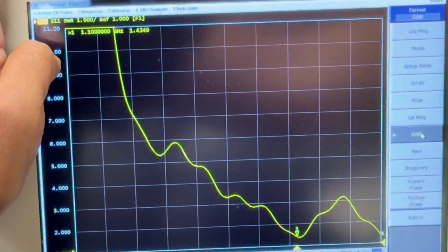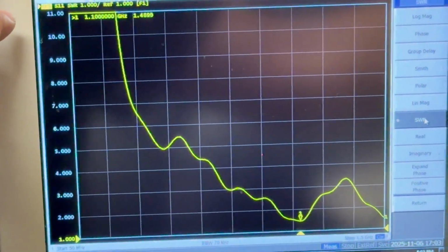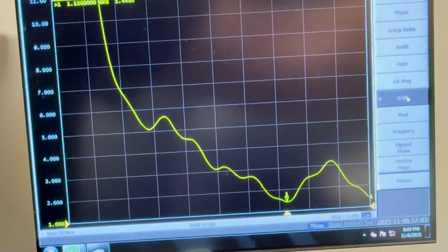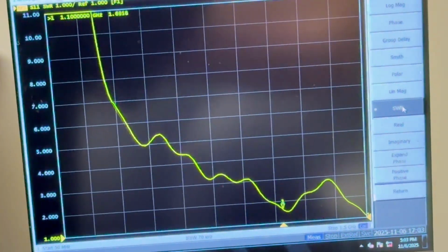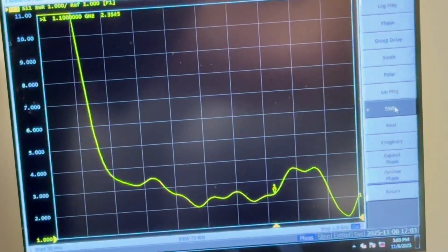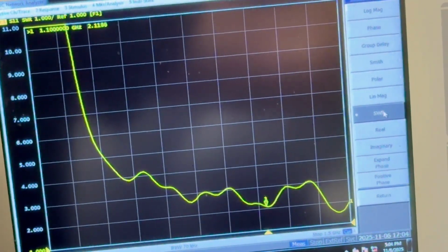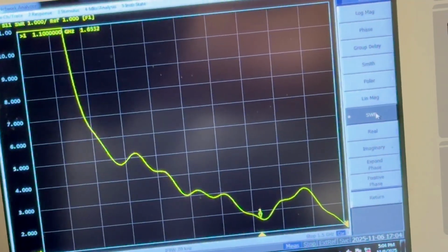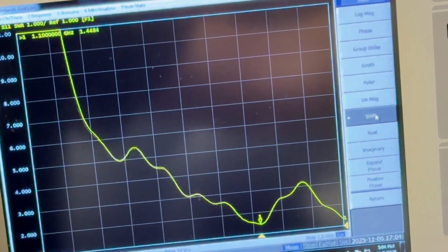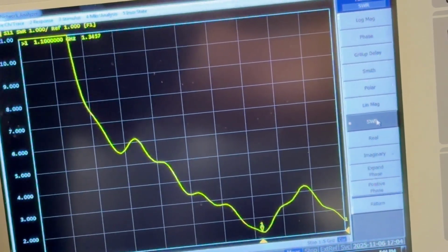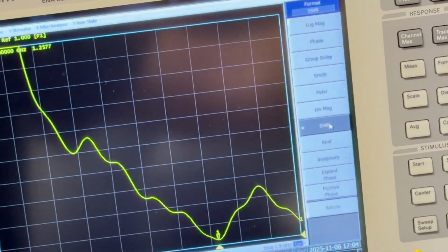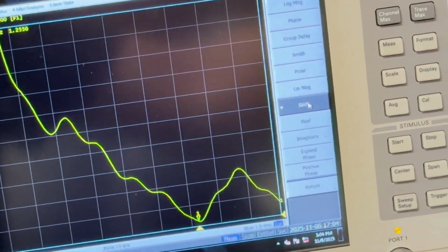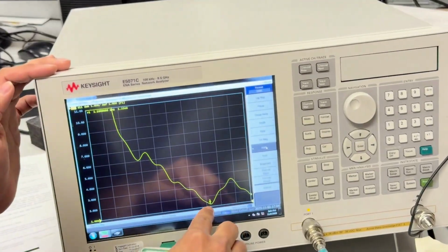So you have to find a sweet spot where you can get the minimum SWR, or closest to 1. There has to be a limit. I think the closest that I could get is, yeah, I'm getting even closer. Yes, so there is a nice value of VSWR. I could get the value of 1.25, as you can see here, and the marker is here.